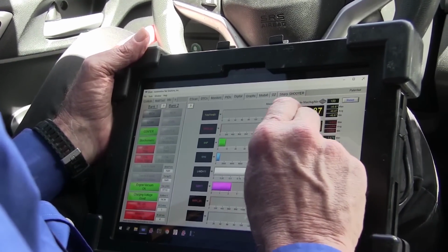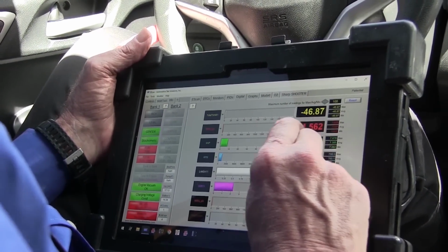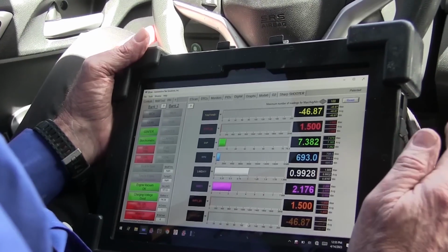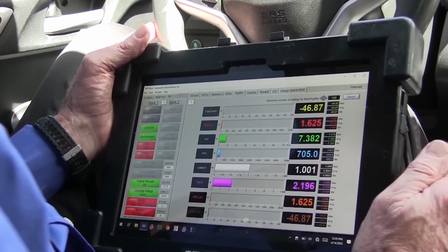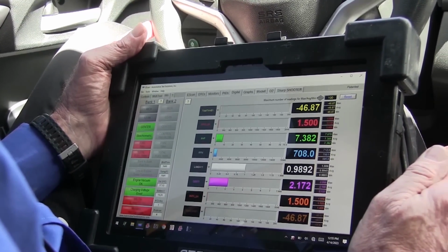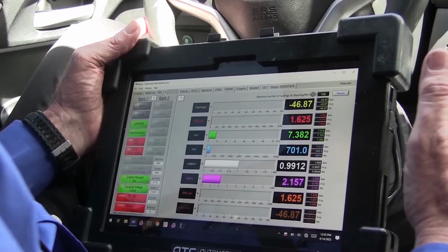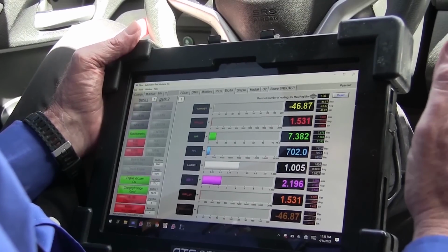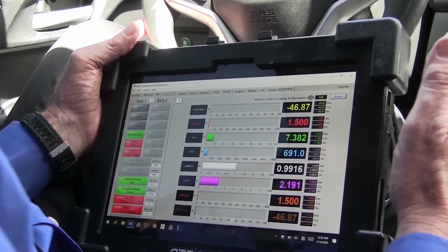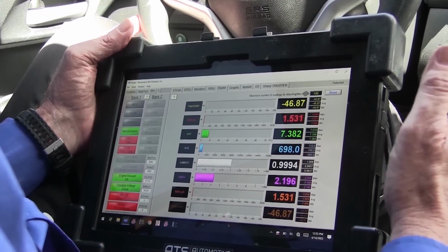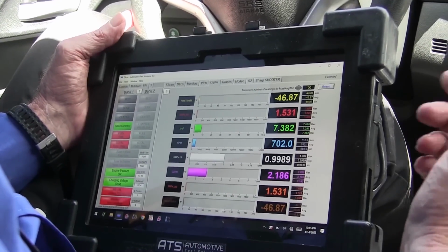So this is a huge takeaway, but it's not air-based, so this problem is not part of the air. We have another problem, and the problem is on the fuel side. This is not an air side. So this isn't the mass airflow sensor, and I think they've already replaced that and a lambda sensor. I don't even know what all they've replaced.